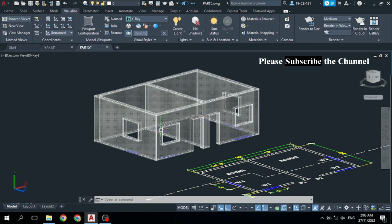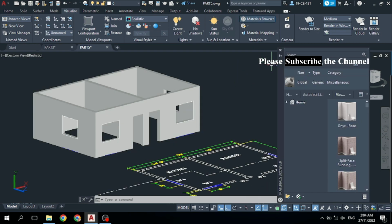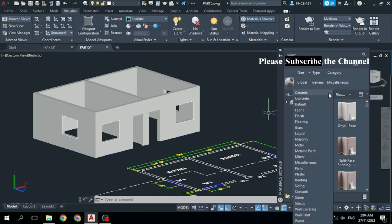So after completing this opening, now I would like to again come to Visualize, and I would be in this Realistic mode. And after that again come to Visualize and click on Material Browser. You can see this Material Browser in the Materials section. Simply click on it. You can see in this small window all materials are available to use for your 3D.